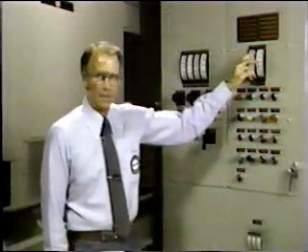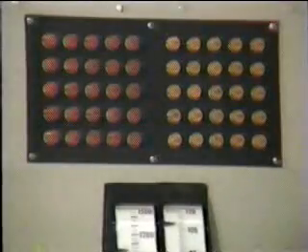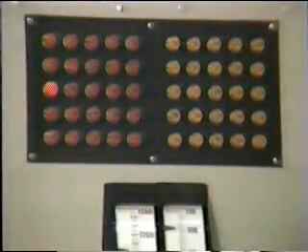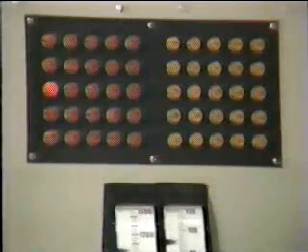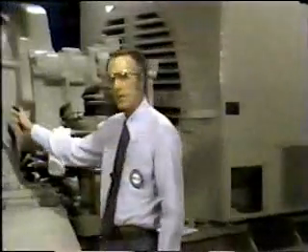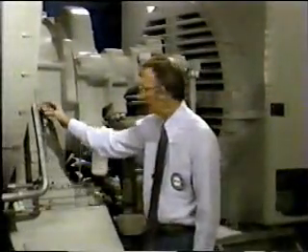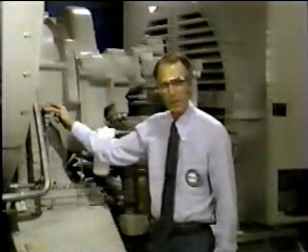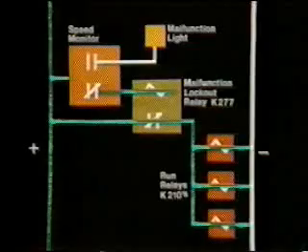The engine is protected from overspeed by 2 separate systems. The first system, part of the engine speed control monitor, will shut the engine down at 108% speed. If, however, the first system fails, the backup overspeed monitor will shut the engine down at 110% speed. You may recall from lesson number 2 that the engine speed monitor G283 receives an input from magnetic pickup G383 located here on the reduction drive gearbox.